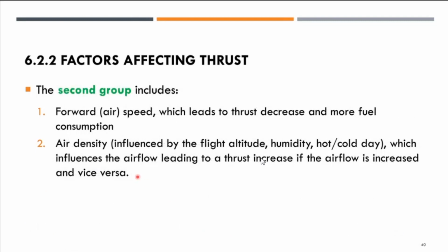The other group includes the forward speed, the aircraft speed, which leads to thrust decrease and more fuel consumption, as well as the air density, which is influenced by the flight altitude, the humidity, hot or cold day, which influences the airflow, leading to a thrust increase if the airflow is increased, and vice versa.